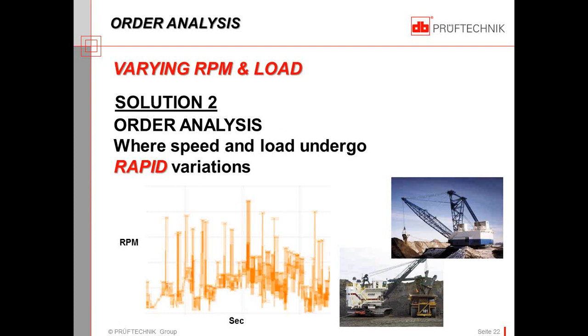In any event, it's an attempt to get some repeatability to the measurement. So that's not something that's uncommon. I've heard of many consultants that do that. They simply come in on a day when there's a PM schedule for the shovel or the drag line, and they simply run the machines at steady state RPMs and collect the data.